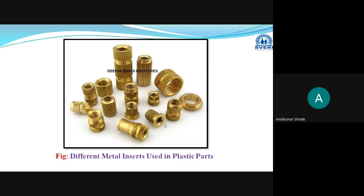So these are the different types of inserts used. Generally, we are using brass inserts. Here you can see clearly on this top surface, knurling is provided so that it will provide adequate support for holding, and internal threading is provided so that it can be helpful for assembly or sub-assembly work.